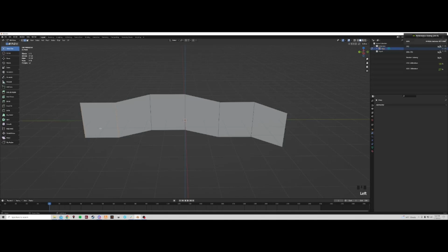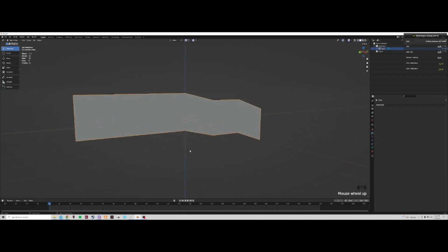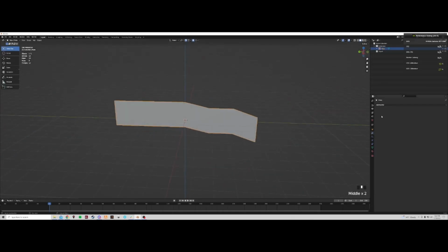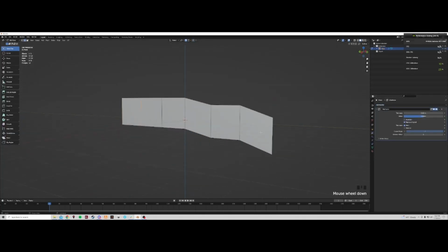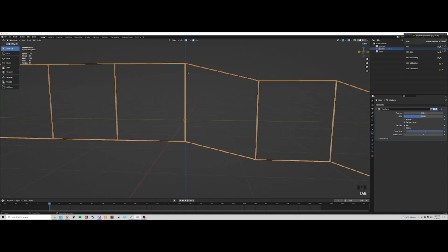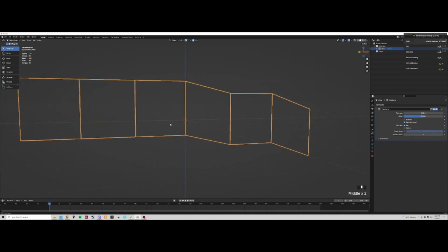So, I don't know. Maybe I got a rail like this, right? This is the shape I would want my rail to be. Okay? I can take this modifier, I can add what's called a wireframe. And what this does is this takes every edge I have on here, now inverts. Instead of this being the mesh, the edge is the mesh. It is the wireframe of that plane I just had.